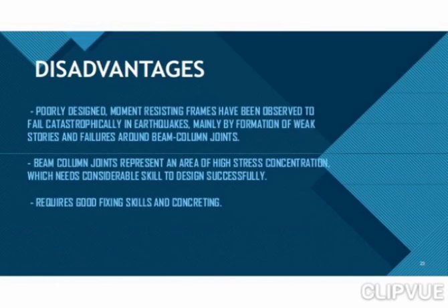Disadvantages: these are basically poorly designed moment resisting frames which have been observed to fail catastrophically in earthquakes, mainly by formation of weak stories and failures around beam column joints. Beam column joints represent an area of high stress concentration which needs considerable skill to design successfully. It requires good fixing skills and